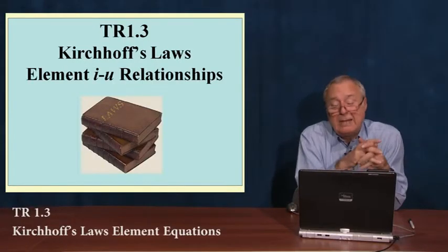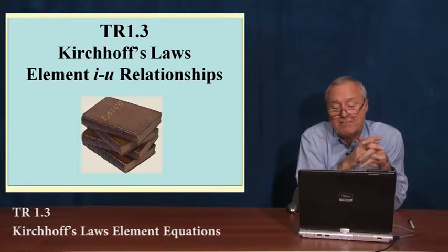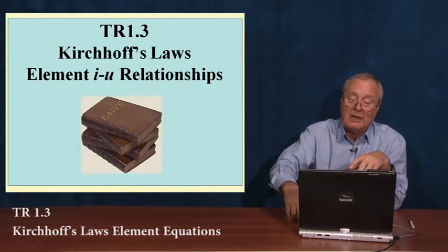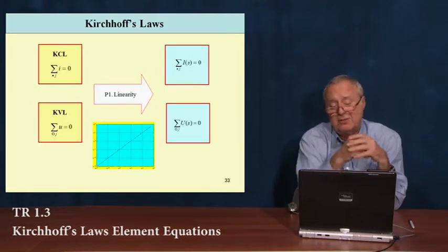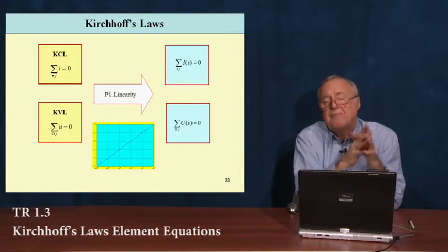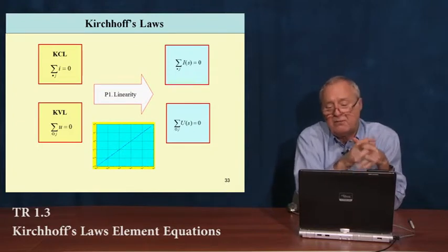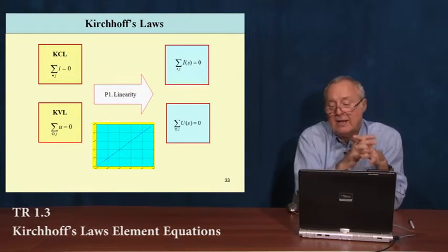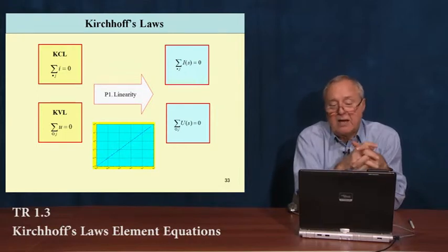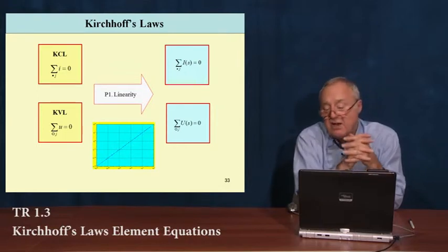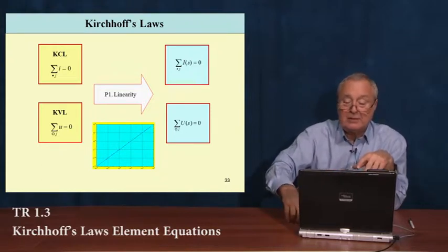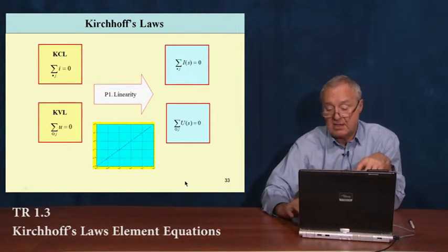Okay, Laplace domain and Kirchhoff's laws, then element I-U relationships for resistor, coil, and capacitor. Well, as regards Kirchhoff's laws, they can be transferred easily from time domain to Laplace domain using the property of linearity. So we may say that for Laplace currents, the current Kirchhoff's law is satisfied, also for Laplace voltages, the voltage Kirchhoff's law is satisfied.